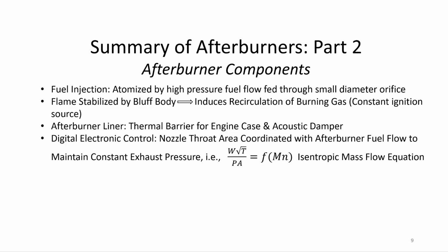And finally, there's the digital engine electronic control. It coordinates the movement of the nozzle with the afterburner fuel flow that's coming in, and the intent is to try to coordinate these such that there is not a significant change in pressure in the back end, because you don't want to stall the engine.